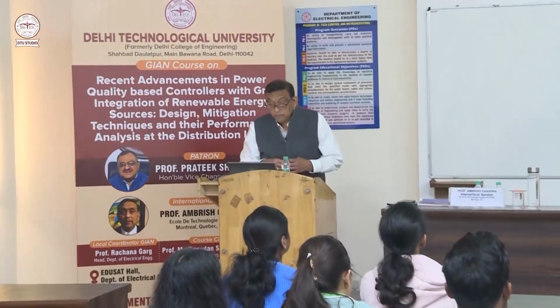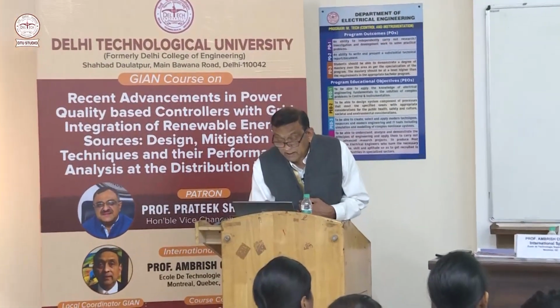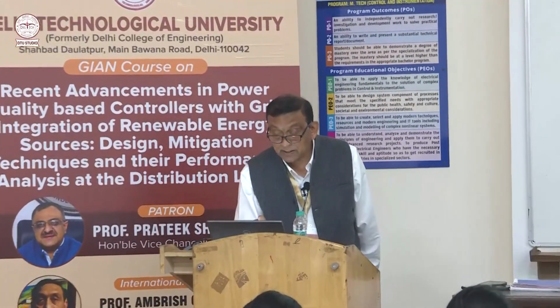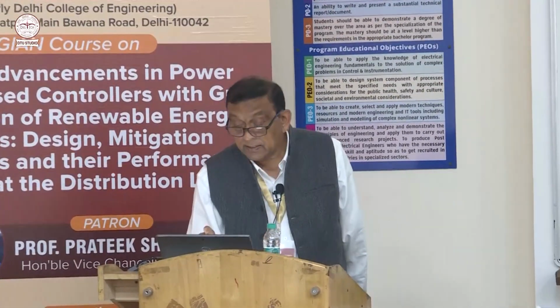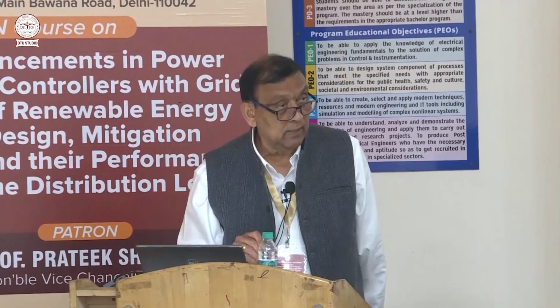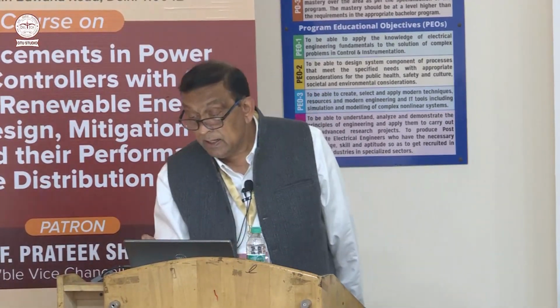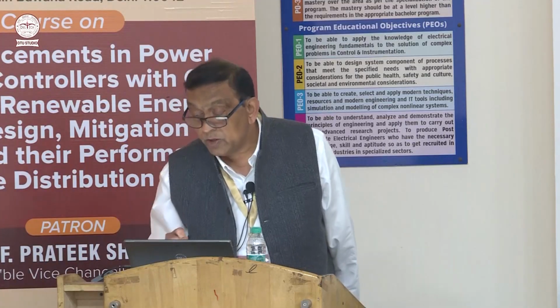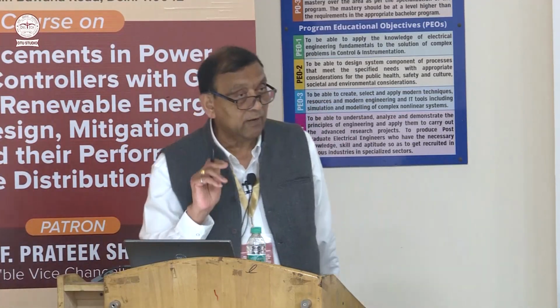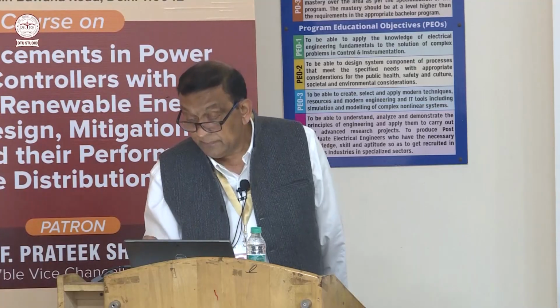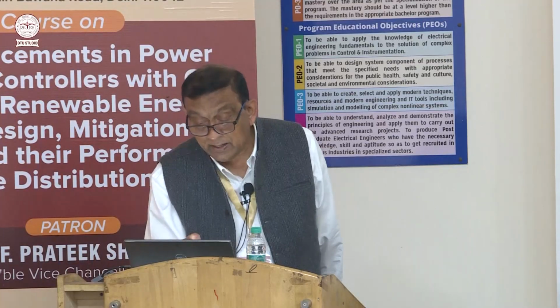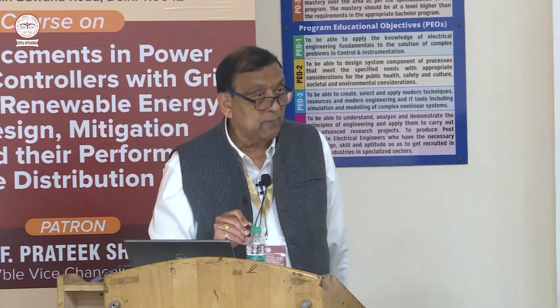Many times we use zigzag connection, delta zigzag. This is delta in the primary. In the secondary, you have a zigzag connection. So what are the zigzag advantages which we have already discussed? That there is no core saturation due to DC component. This is the big advantage of zigzag connections. No zero sequence current in delta in the primary side.